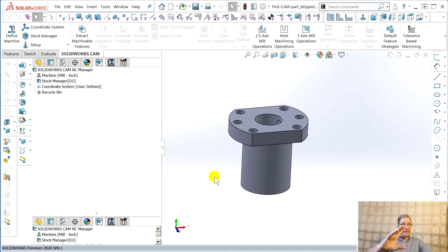If you've pulled it out of the vise for any reason, when you put it back in, you could be a few thousandths off, or one thing happens, a chip goes on the parallel where you're setting it. You set the part on top of the chip, now it's 5 thousandths off. That's why good machinists slide it along the parallels to hit that stop, so they're sure it's down and it feels good. So you got that problem.